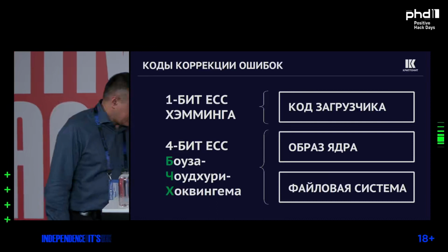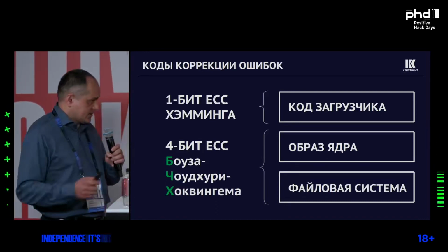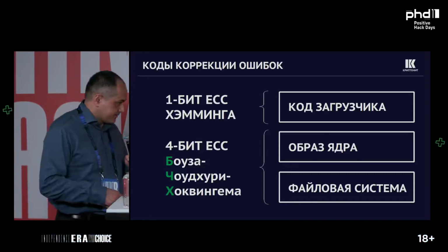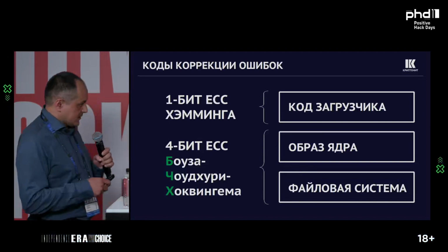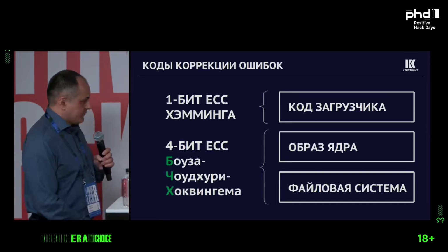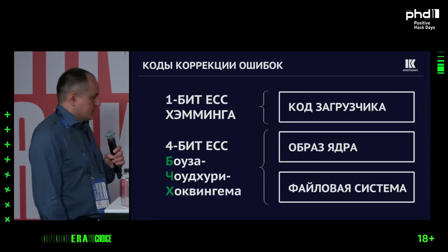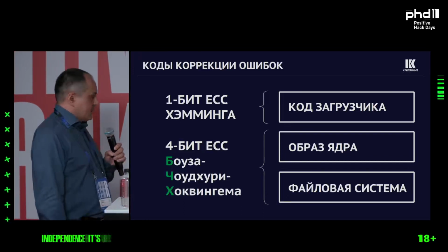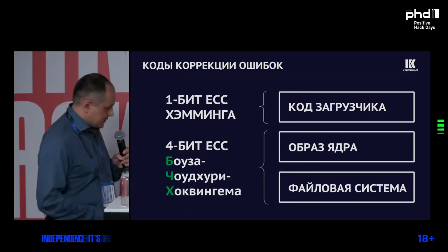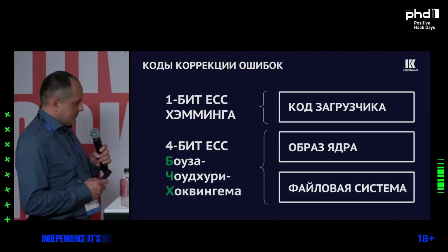And in some cases, the loader is placed in a number of places, and it can read from different places, checking whether the checksum is okay. Thus, the error correction is delegated to FlashFX. The second type is the ability to fix 4 bits for 512 bytes.